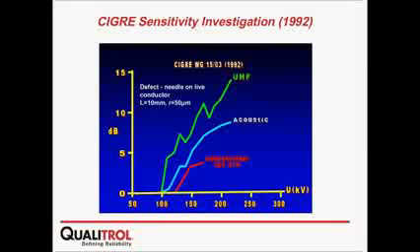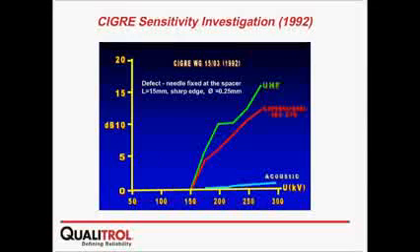In acoustics, you have a lot of attenuation, so UHF would fit better. For other defects, with a needle fixed on the spacer, as I mentioned before, acoustic cannot detect it. The conventional method would be able to, but again, it's as I mentioned before.